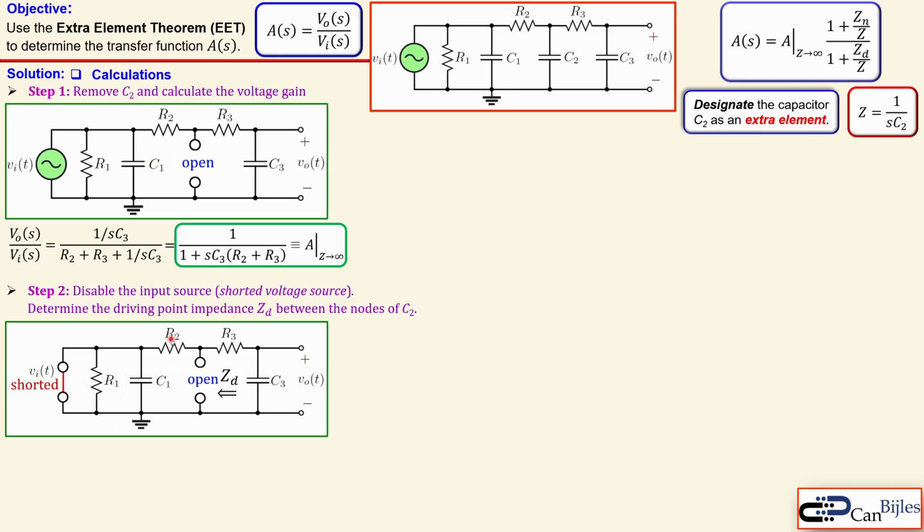That means actually that you see here to the left, you see the R2. But you also see here the right side, you see R3 in series with the capacitor C3. That means actually the following. So the R2 is actually then parallel to the series combination of R3 and C3. And that's actually what you see here. So the R3 is in series with the capacitor C3, which is then the reactance of this capacitor, in parallel with this R2, which is then actually shown here.